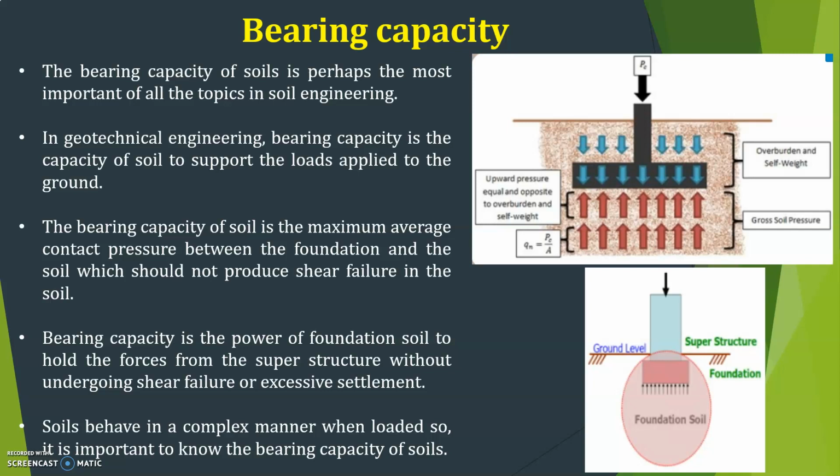Loads from buildings are transmitted to the foundation by columns, by load bearing walls or by such other load bearing components of the structures. Sometimes the material on which the foundation rests is ledge, very hard soil or bedrock, which is known to be much stronger than is necessary to transmit the loads from the structure.